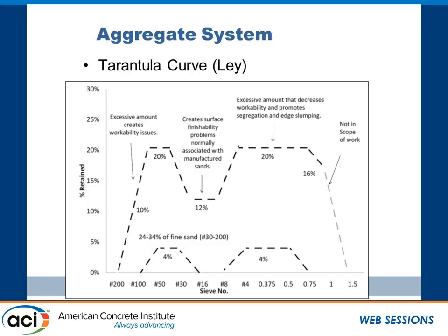It's not the 8-18 curve that you may be familiar with. The top end is at 20, not 18. The bottom end is at 4, not 8. And there's this hump in the middle where it goes low. And Tyler's position is that if we get a gradation inside this curve, we're going to be a lot better off in terms of fresh properties, workability of the system.